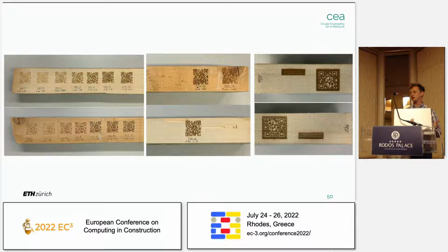With the Trotec machine that we had, the two big parameters were both power and speed. So you can see on the left side where we kind of played around with these parameters. But we also wanted to explore if you were engraving on something such as the knot of the wood or on a chipped piece of wood, would that affect how readable it was?